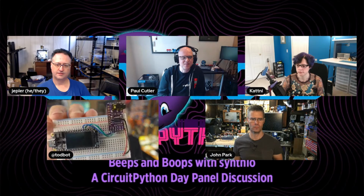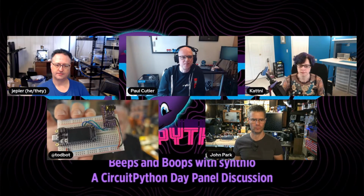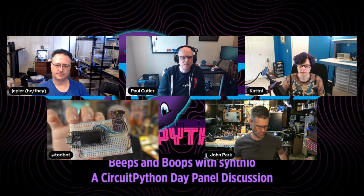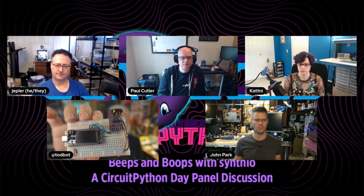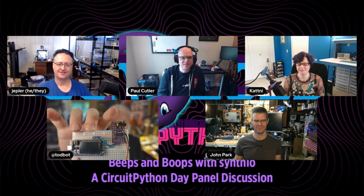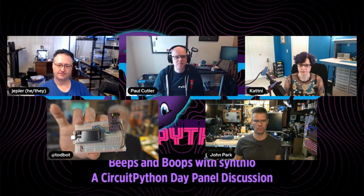ESP32 with I2S is that now you're in stereo. The other one was in mono. This can go up to 44 kilohertz at 16-bit, so it's higher quality, like it's actual CD quality in theory. And I think the ESP32 can do 44 kilohertz synthio. I've not tried it yet, though. I'm kind of a lo-fi guy. But these things are pretty cheap also on Amazon, and all it requires is 3 wires instead of 1, and you get stereo.